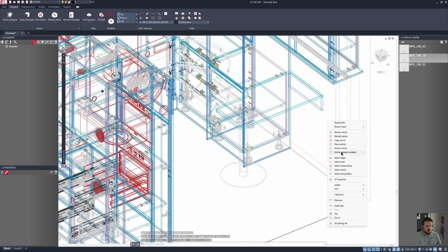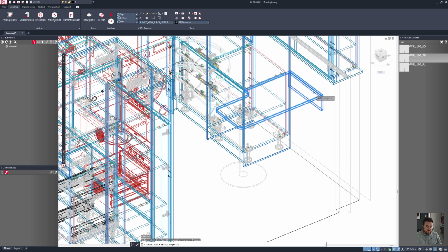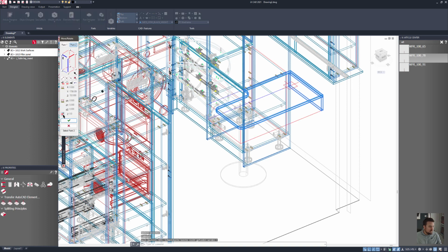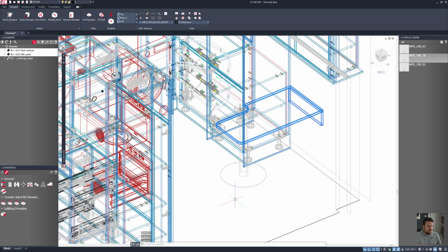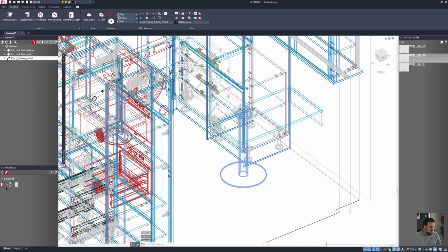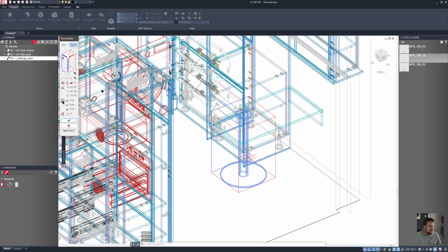So in here, I'll select parts, these two parts and this part, and I can grab these two to begin with, and use the move command to move this in Z minus 172, and then click tick, and then I'll do the same for this. So rather than it being a tall breakfast bar, in this case, it's now just a table height little nook for someone to sit on.